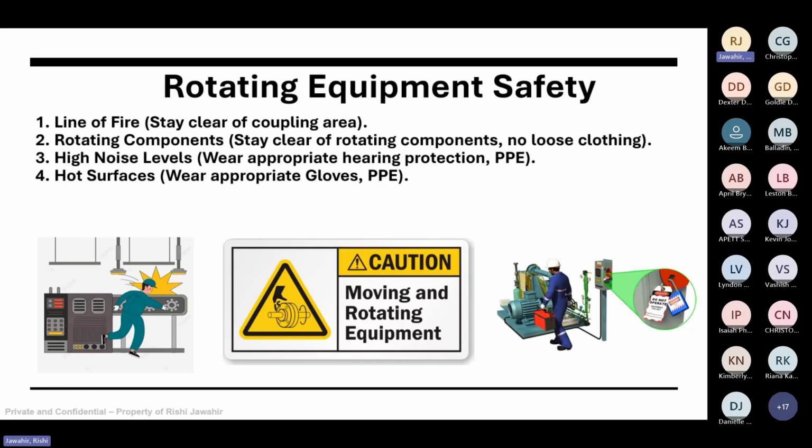So ensure you have the appropriate PPE, whether it's earplugs, earmuffs, or double hearing protection. Also, hot services: if you're around steam turbines, gas turbines, hot process conditions, process condensate pumps, or any kind of hot process area, ensure you have the appropriate gloves around hot services.